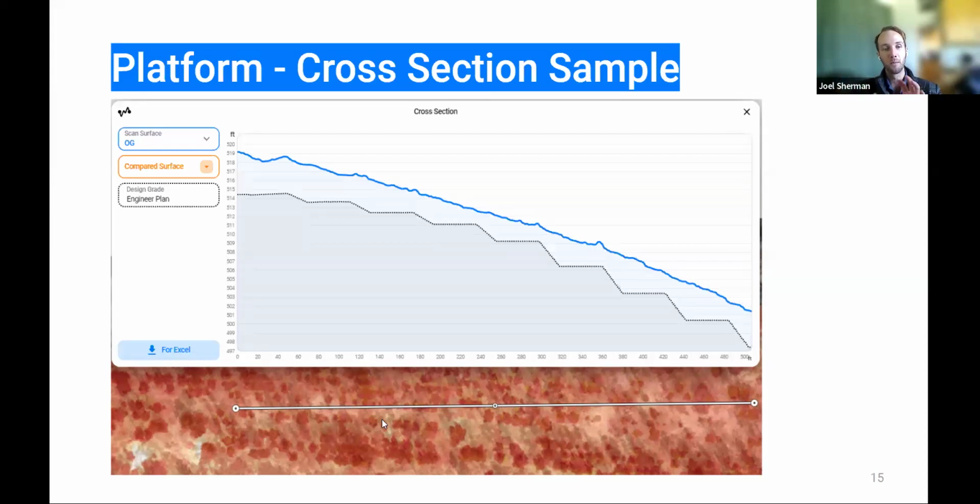So this is the more useful component than the cross-section tool, because you're able to truly quantify the discrepancies in the design versus the original grade data, and quantify what your net import-export could be like in a numerical sense, right? And not only just in a visual sense, but in a numerical sense. And you can see how you potentially need to move soils across the site.